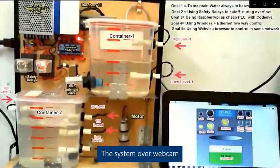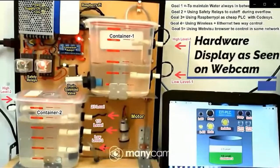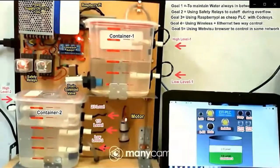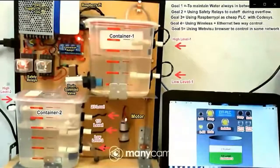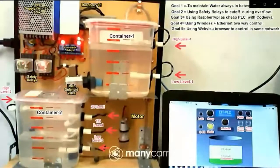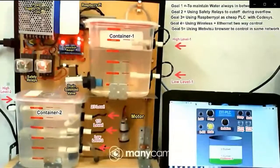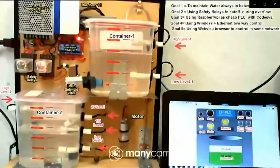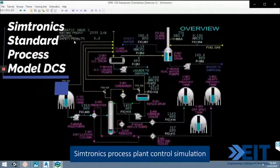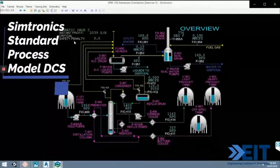This is a couple tanks one. This is a hardware experiment, couple tanks, a classic process control exercise to begin. We're using a Raspberry Pi here to host CodeSys software, a good quick and easy introduction to some ladder logic, standard software used in PLC programming. We also have established a proper safety relay latching system to control the overflow, underflow sensors and pumps on that tank. That was the human machine interface for that shown.